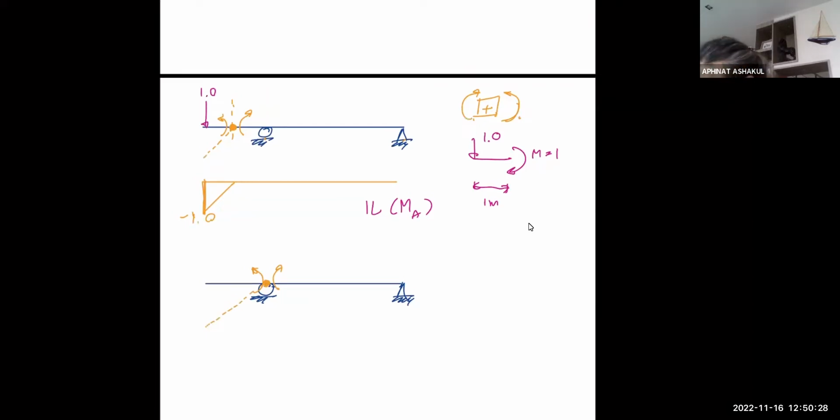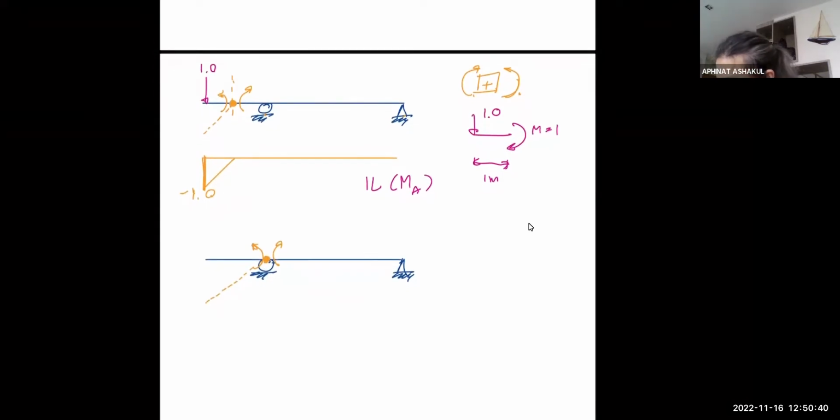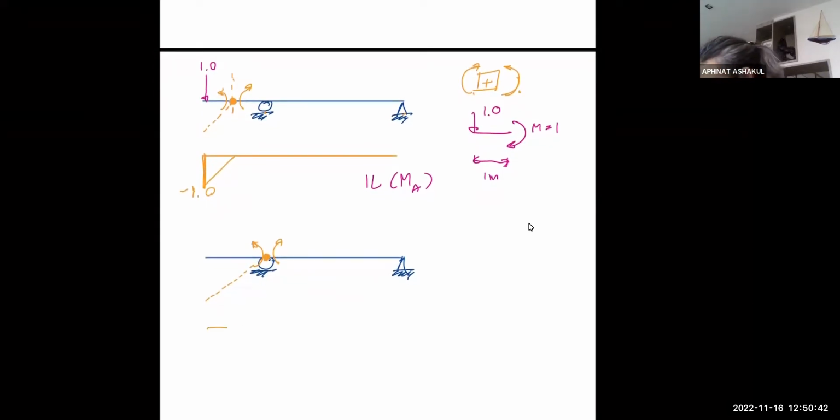But on the right side, on this piece, because you have the restraint on both locations again, it can't go up. So it has to remain 0. And therefore, your influence line now looks like this. Notice how similar in shape the influence line of MB is to that of MA.